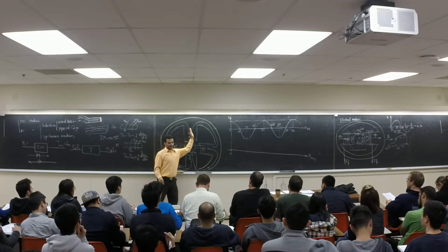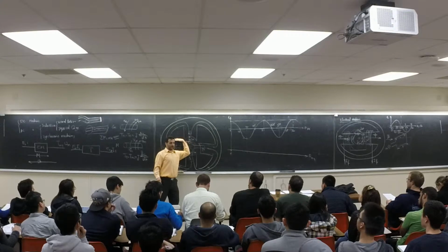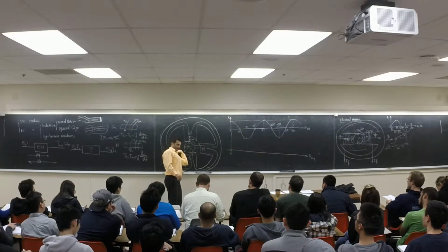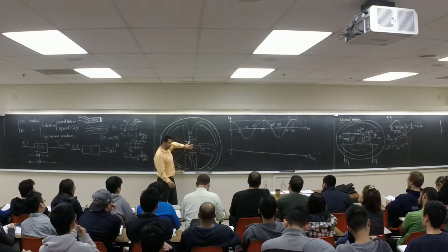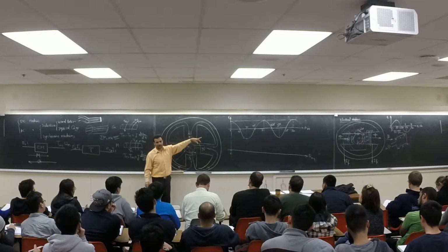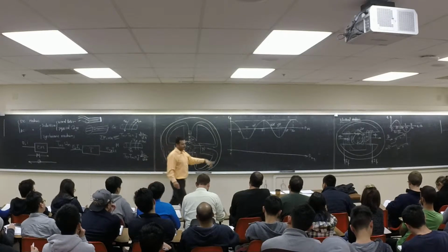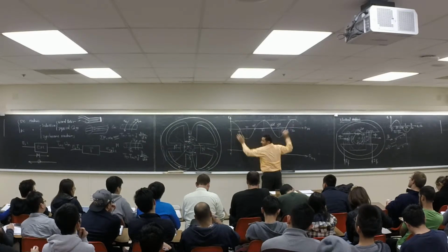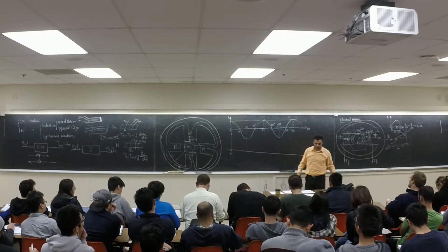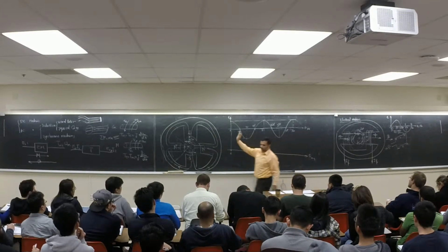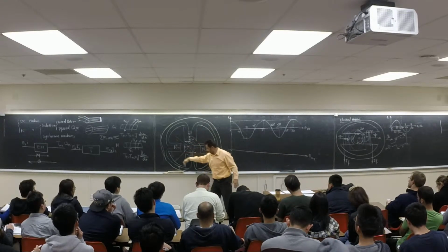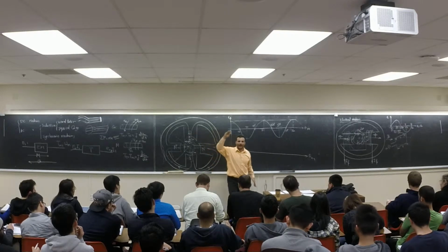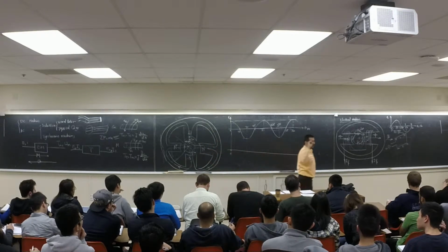Here is a 0 mechanical degree, right? This is a 45 mechanical degree, right? And here is a 90 mechanical degree, right? See, I'm rotating this one mechanical, but I made a mistake. It's not electrical, right? But see, this is a 360 mechanical, right? So see, I moved from here, I went one full turn, 360 mechanical. Well, look at my electrical waveform.